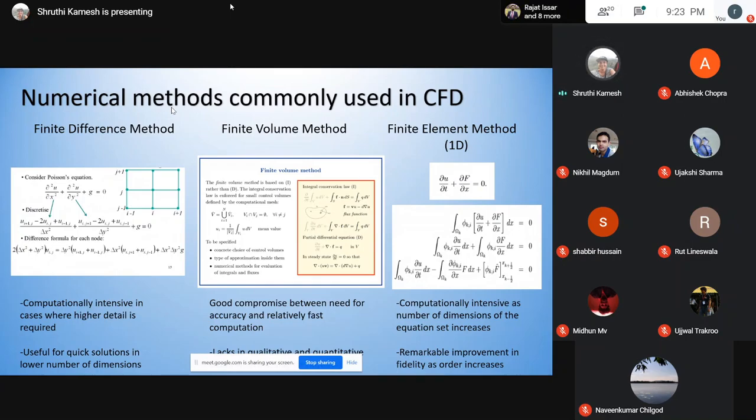Finite volume and finite element are weak, which is that they reduce the constraints on the boundary conditions of your governing differential equations, and they make sure that you have probably a set of solutions to choose from. Now, which we can choose as the right solution depends on what is physically satisfying. And what we say in the world of numerical methods is that it should be entropy satisfying. It should not be entropy violating.